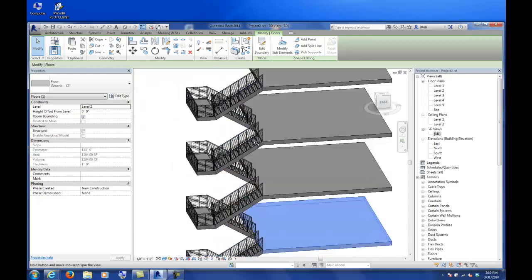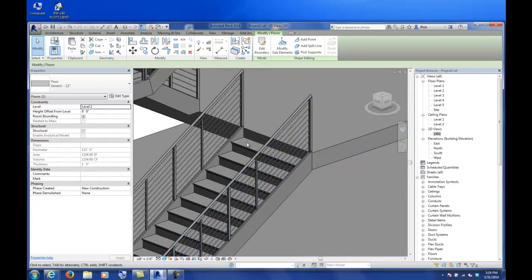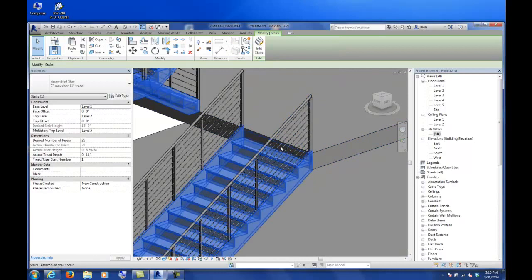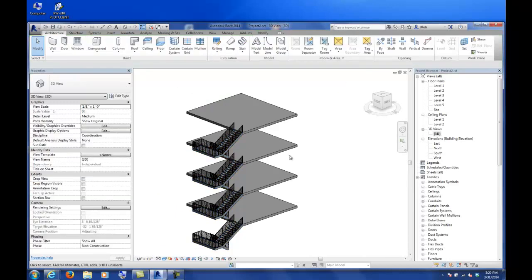Now if you wanted your top stair to be a particular tread, a lot of times what we typically do is have your top tread at the same level as the floor, and then the floor would butt into that, so that all of your surface nosings would be the same through the flight of stairs.